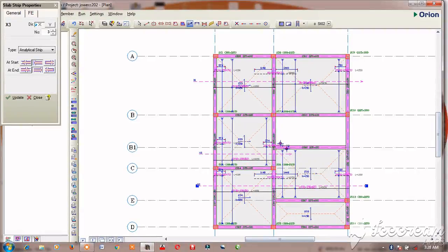So I have done this one as well. The depth of this slab, they are all sufficient for this design. For this one now, let me do this one. This one is continuous here, but it's discontinuous here. At the start here it is continuous, but at the end it is discontinuous. So just come here, click it, then hold your control key, then leave it here. So that one is for what is sufficient.